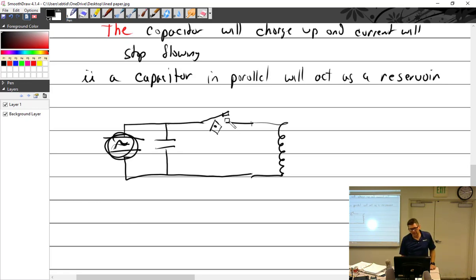And so what would happen is every time you started to open these points, because there's so much voltage, as you're opening it, the voltage is going to jump across the gap, and it's going to burn and arc those points as they open up. But with the capacitor, what happens is as these points start to open, all of the electrons, which are flowing out of here, headed to the points, they see that the resistance starts to build up on those points. And as that resistance builds up, the electrons are going to realize that the capacitor is a much easier route to go. So they kind of turn around, if you will, not really, and they start filling up this.